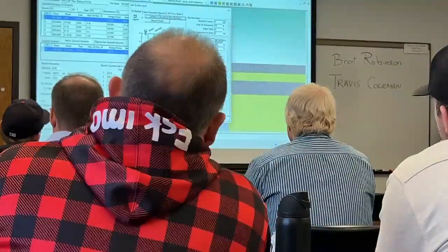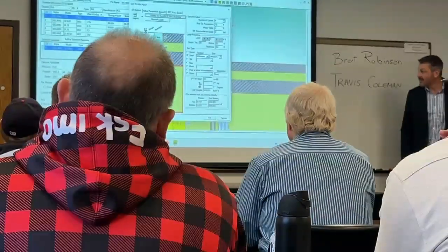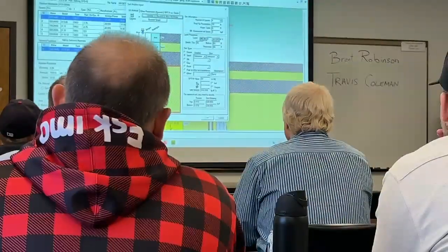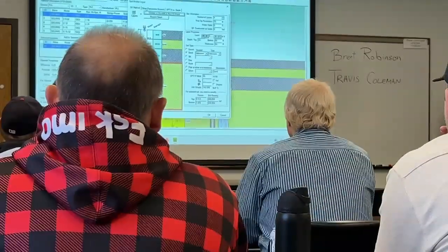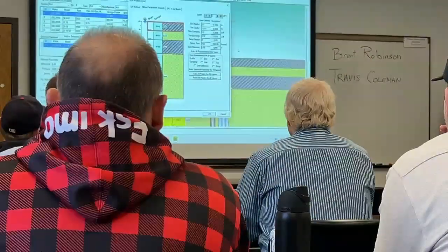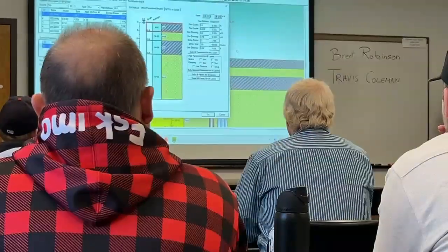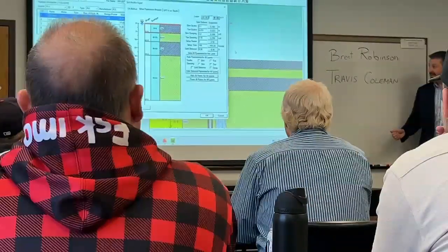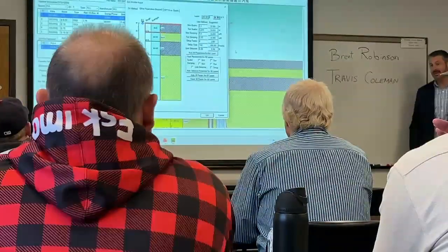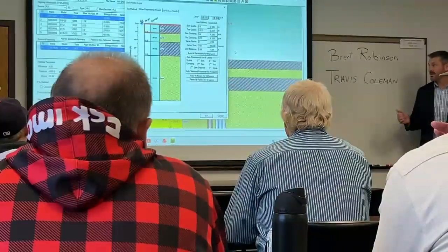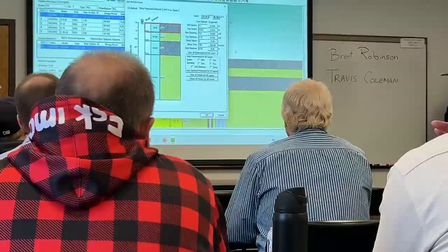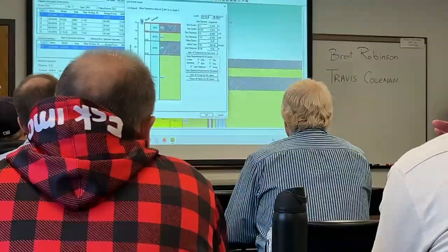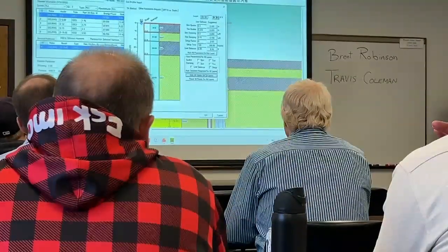So what I've not made considerations for are the dynamic parameters of the soil. So this is going to give you some recommendations. Among other parameters, it's going to say these are the recommended quake and damping values that I recommend for these soil types, which also accounts for their soil strength. So I'm not going to spend a lot of time trying to figure these out. I'm going to auto all parameters for all layers.